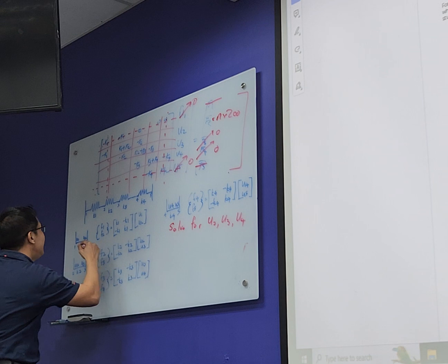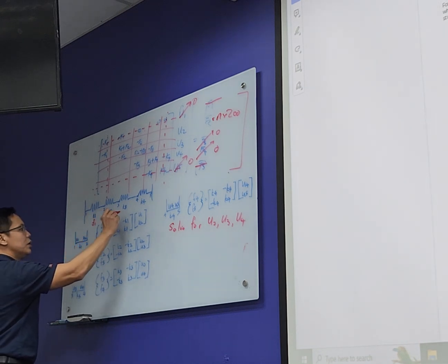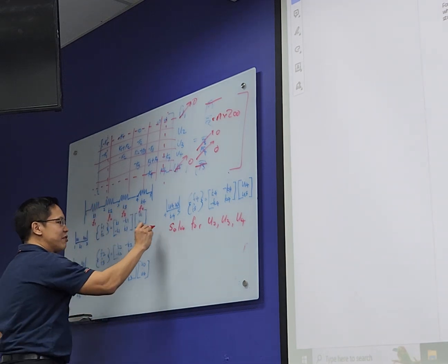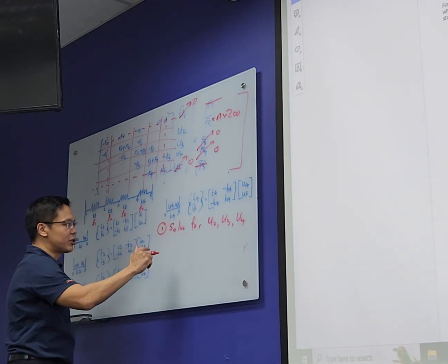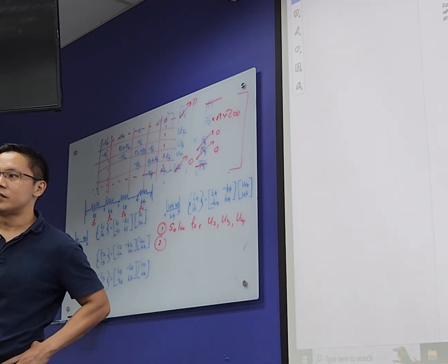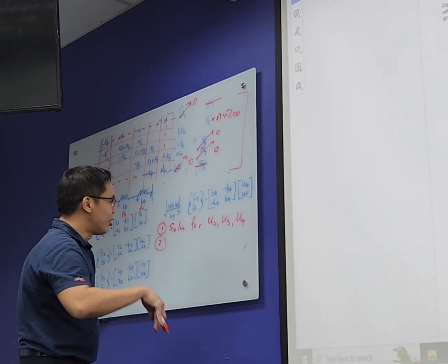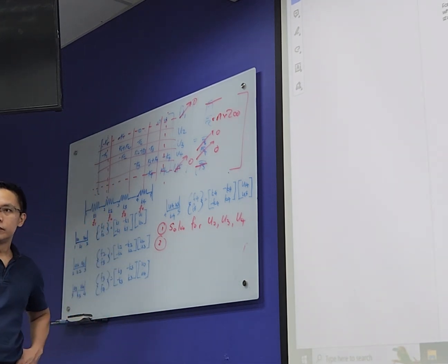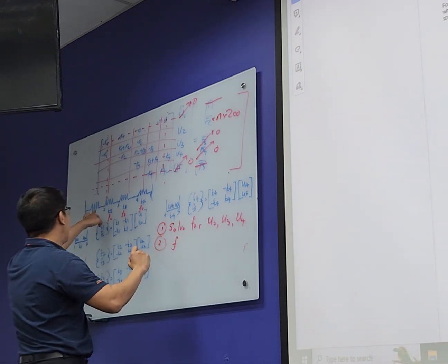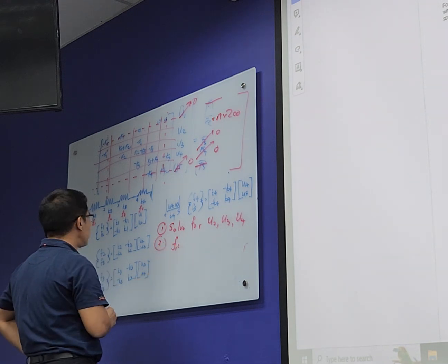Which we said previously, right? Just now we said the spring force equals to what? F1, F2, F3, F4, correct? So this is the first thing to do. There are three parts to this question. Second part, how do you find the spring force? EA over L. Before that, F equals K U. Let's say F1 equals to what?